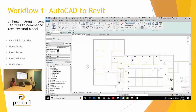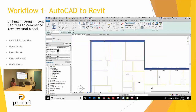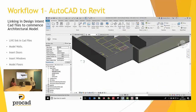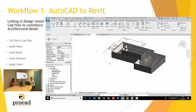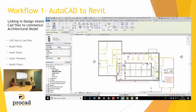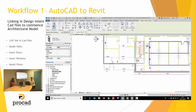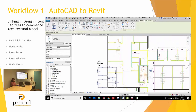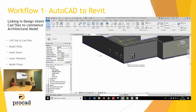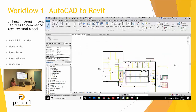And from that, going to create the floors. Floors are generated using the wall functions as well, selecting your profile, following the traces of the wall, simply creating the floor. And last but not least, in this workflow, just simply adding windows. Windows are the same as adding doors. You simply hover over the wall and select, and that automatically places in the window like so.